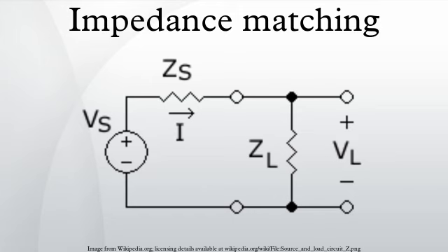The magnitude of the impedance ratio is limited by reactance losses such as the Q of the inductor. Multiple L sections can be wired in cascade to achieve higher impedance ratios or greater bandwidth. Transmission line matching networks can be modeled as infinitely many L sections wired in cascade. Optimal matching circuits can be designed for a particular system using Smith charts.